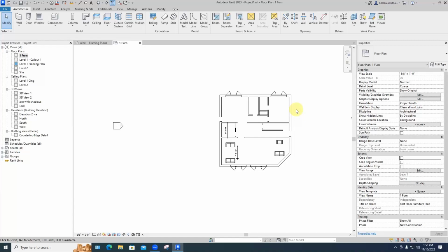So when we're making 3D families in the Family editor, which are the ones that we'll save to disk and can share and pass around and use in further projects, and also include them in the furniture and other schedules that Revit automatically generates, we do that in a Family editor, which is a little different from this project editor.